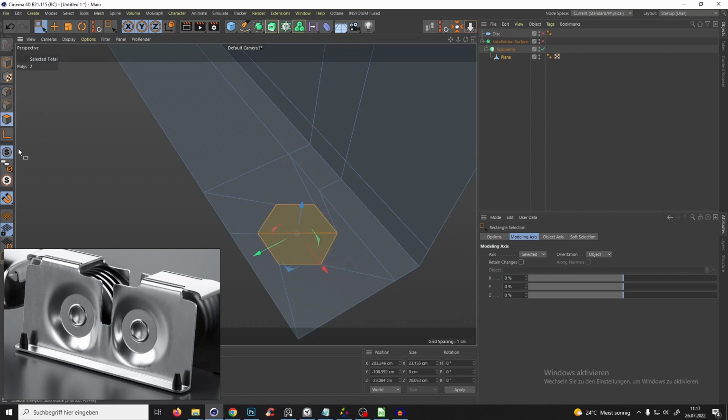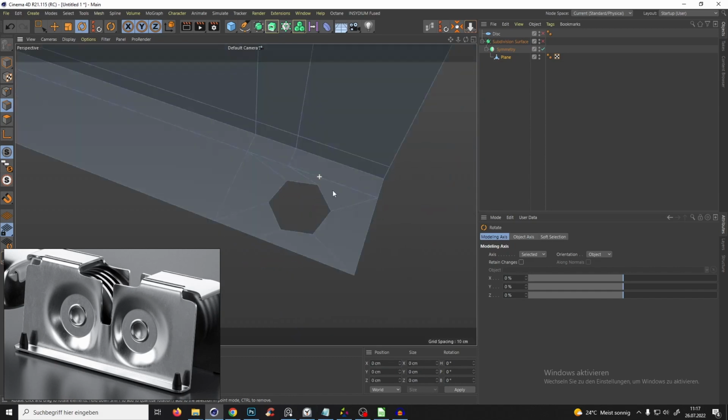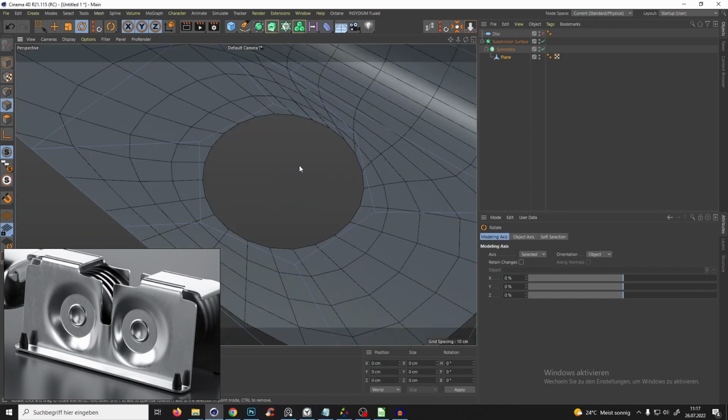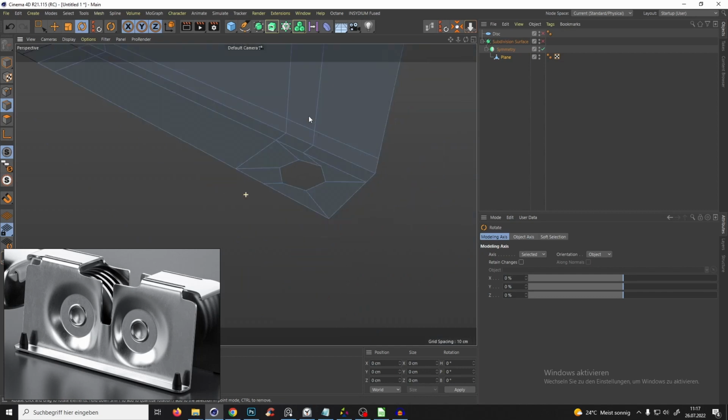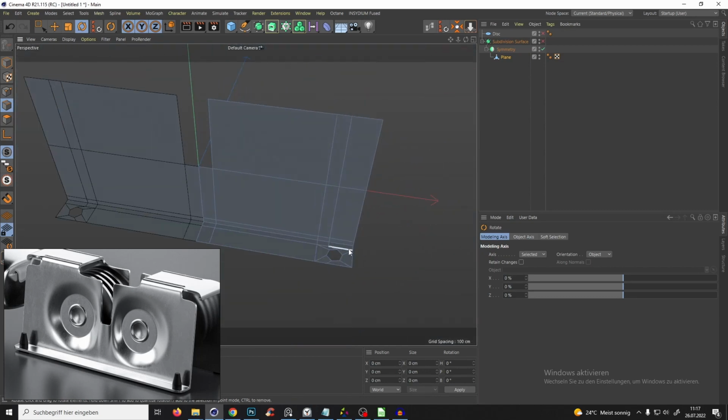And also we can just go to polygon mode and just delete them. And let's rotate these. We disable a snapping tool. Let's just rotate it a little bit with selecting the edges and R for rotate. So this is just a little bit more straight. And if we press now subdivision surface, you see it is a perfect hole. So yeah, we have something like that here.